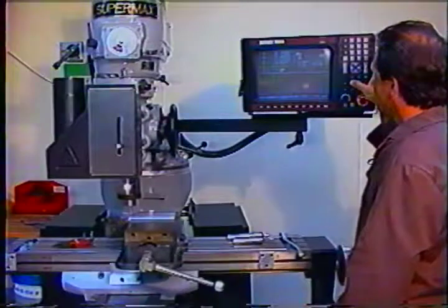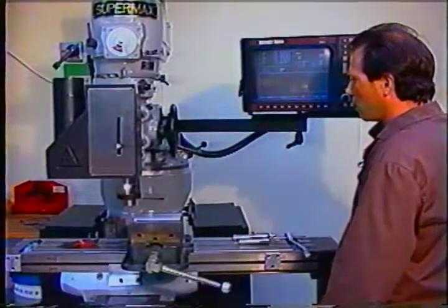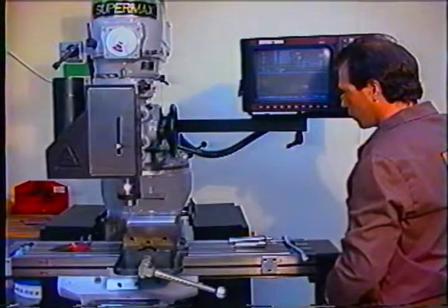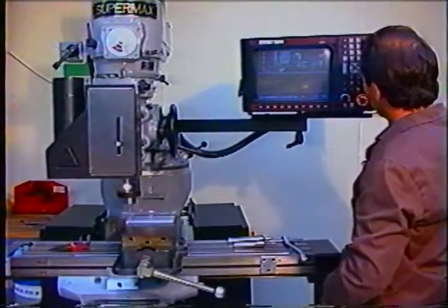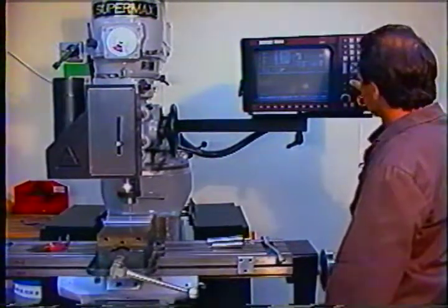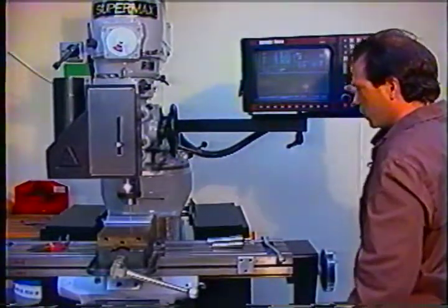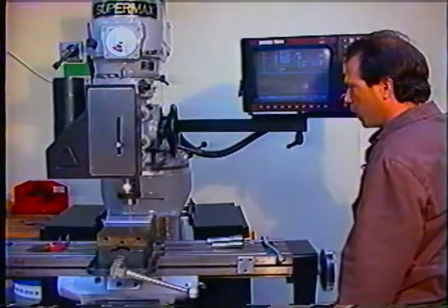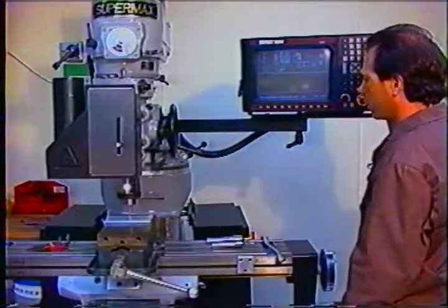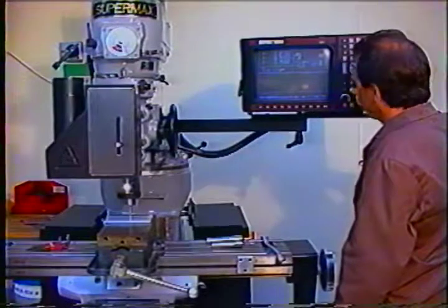Now I will toggle my jog status back to feed and move away from the part in X, and I'll come around to the solid jaw of the vise here. I have to raise Z up a little bit and move down here. We'll slow down the feed rate a little bit and bring Z down. I'm just going to find the positive edge of the workpiece here for Y-axis. Again, I'll get close and I'll turn the spindle on, forward. Go to 10 thousandths jog at a time, and I move in.